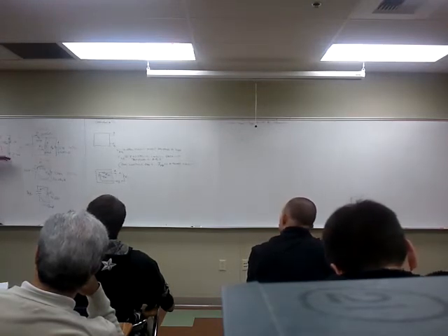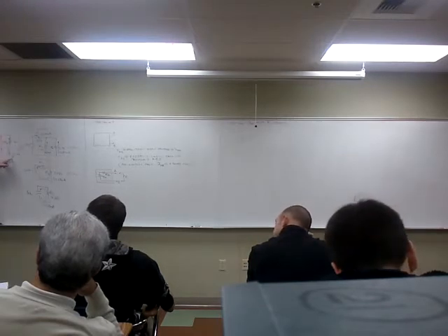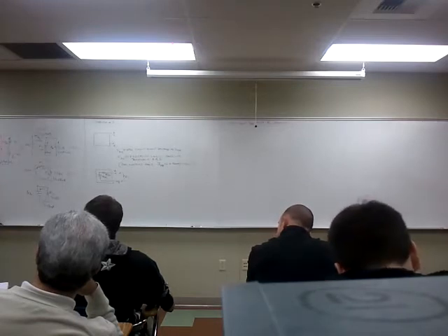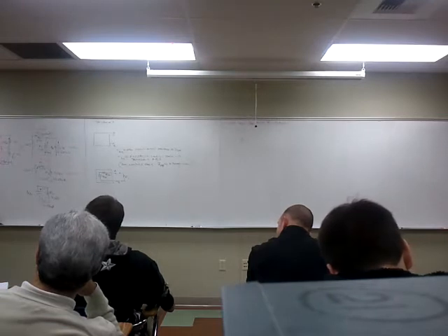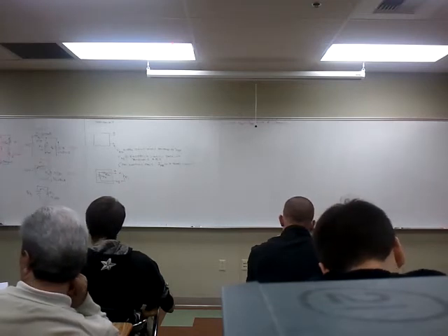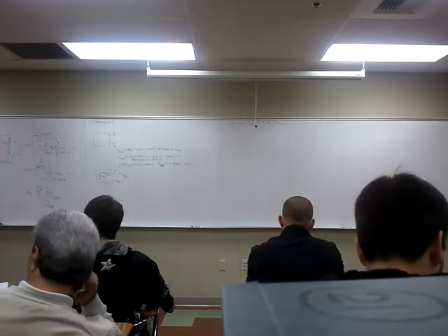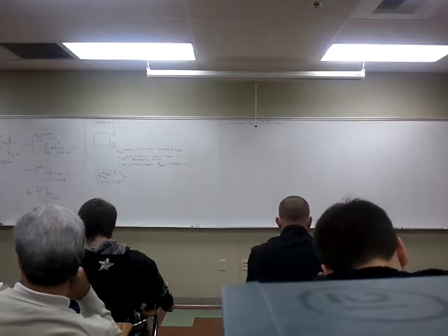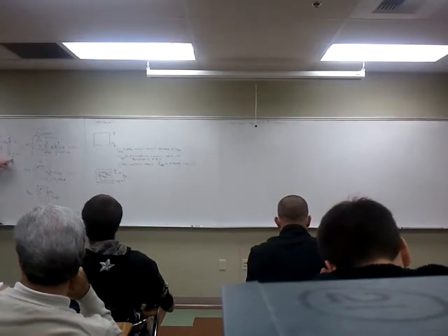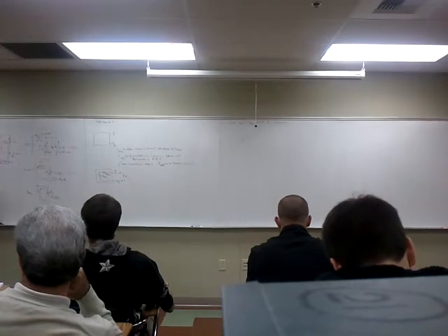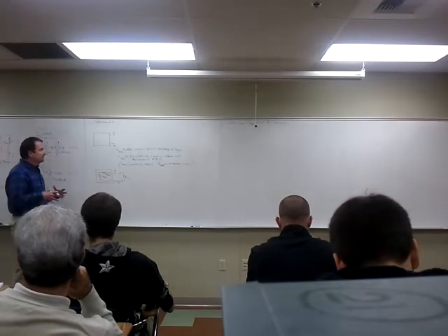It's like this could be an amplifier, and that's the 8-ohm speaker on the output. This could be an instrumentation amplifier or a motor amplifier that drives a servo or a stepping motor or anything. Something that drives something else. That's a very common thing in the world of electronics. It's sometimes difficult to explain at this point, but you kind of have the idea that circuitry might control a DC motor, and the DC motor does something based on the circuitry. Well, this is like the motor that's being driven by the circuitry. And I'm just showing a bunch of resistors because that's all we know at this point. So RL is the resistor of interest.